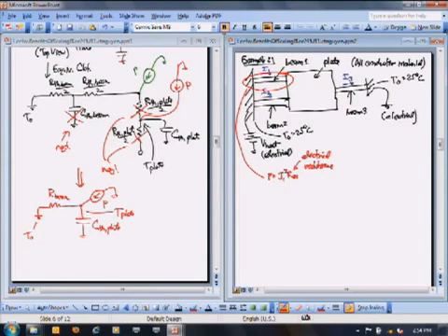So now let's go ahead and make an equivalent circuit for this whole thing. What's that equivalent circuit going to look like? Well, I've got two beams here going to ground. And I've got first my plate here. So the plate, if I wanted to be complete, hint, I'm going to eliminate my completeness very soon, can be modeled again by this T network of elements. So that's the thermal capacitance of the plate, and I'm going to have some thermal resistances for the plate. That plate now on the left side is going into two beams.